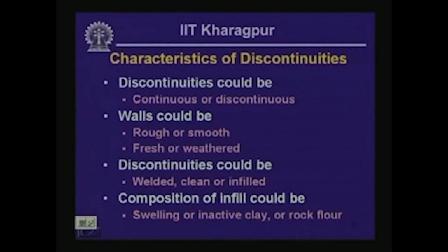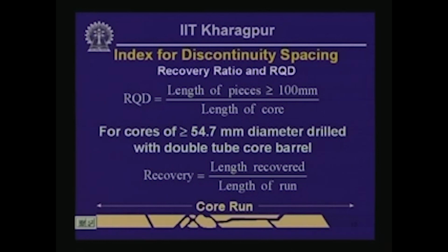They are basically non-clay particles. They are fragments ground up from the relative movement of the two parts of the rock across the discontinuity itself, and that also could be another type of infill material within the discontinuity. Okay, so we have to consider all these aspects when we try to look at the behavior of a discontinuity.